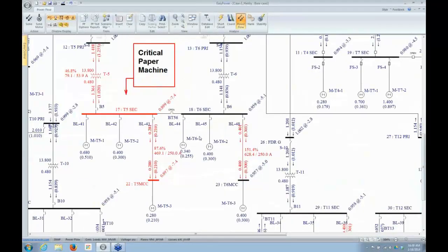All right, so let's look at a couple more what-if things that we can do while we're in PowerFlow. One of the other options, if I'm trying to improve my voltage, is I can change my transformer taps, right?